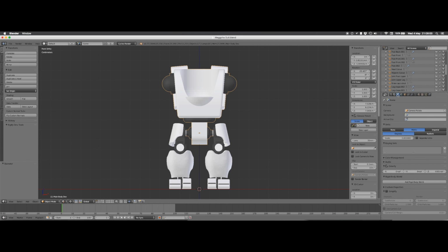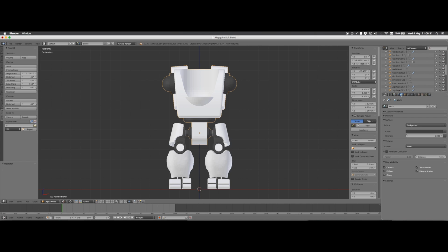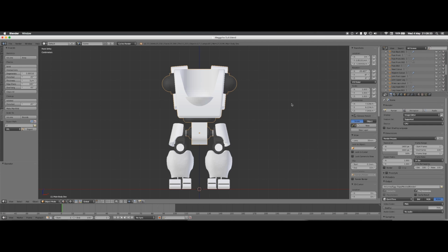Now, as always, I click multiple times to get to something. I like to have the scale set at 0.001. That just means that when I go to the 3D printing tab and click on export, it exports to a file nicely scaled for what my printer's slicing software is used to. I also have it in metric and degrees because that's what I'm used to. That's pretty much my basic settings.